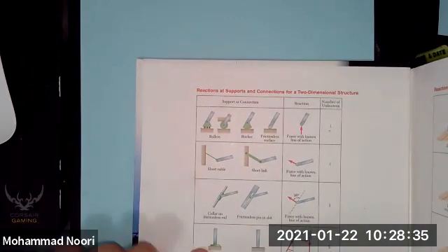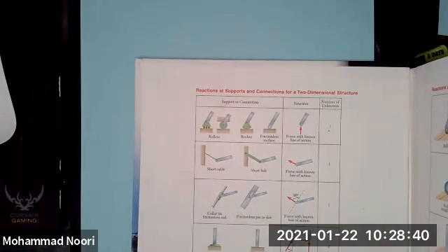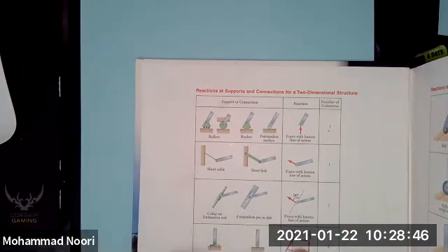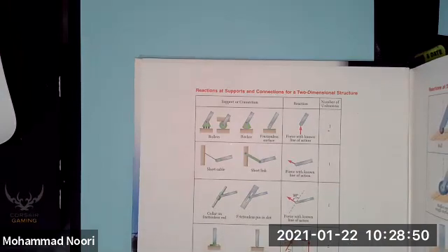We'll get to that. But this pin or hinge, or if you have a rod sitting on a rough surface which has friction, doesn't resist motion in this direction, represents two unknown forces. And of course, a fixed support represents three unknowns.